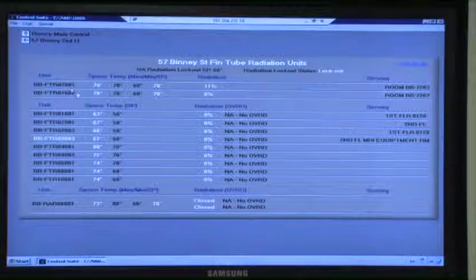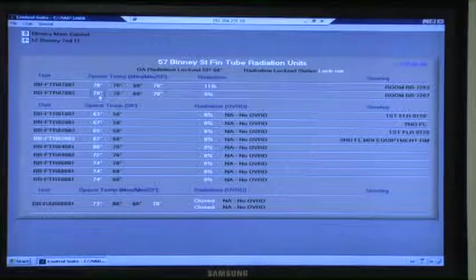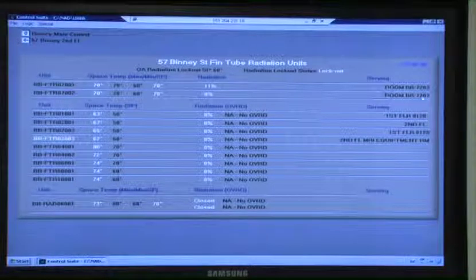Okay. Are these the room numbers from the right side? Okay, so 703. These are the rooms that it's serving, and it shows us the space temperature. Is that space temp? Yes. Then you have your min and max set point, so the person could change the temperature setting, but only between those limits. Those two aren't behind the elevators. Those are a janitor's closet.